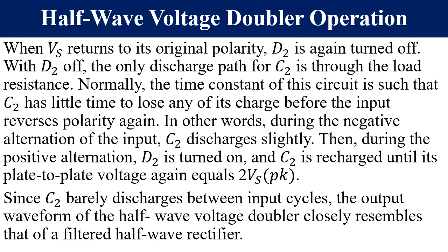We are continuing on the operation of the voltage doubler. So we can see that the capacitor C2 discharges through the load after being charged to the supply voltage from the input and also the supply voltage from the capacitor. So what are we saying? When the capacitor is now discharging, especially C2, it is now supplying power to the load, and we've got what we call the time constant.